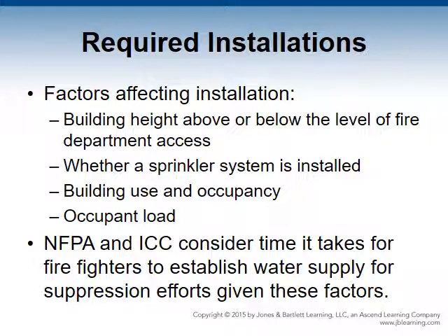Many factors affect installation requirements, such as building height above or below the level of fire department access, whether a sprinkler system is or is not installed, the use and occupancy of the building, and of course, the occupancy load. Both NFPA and ICC consider the time and effort it takes for firefighters to establish a water supply for suppression efforts, given the factors above.